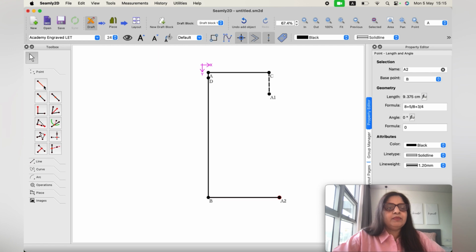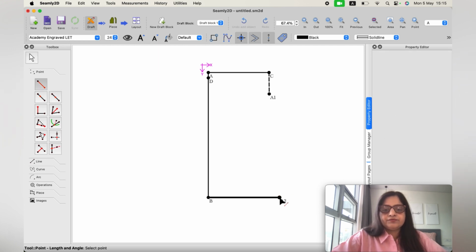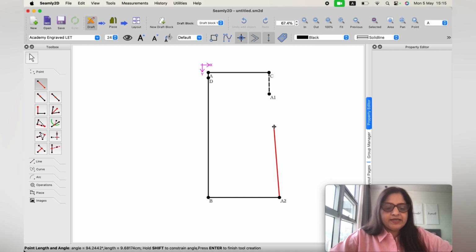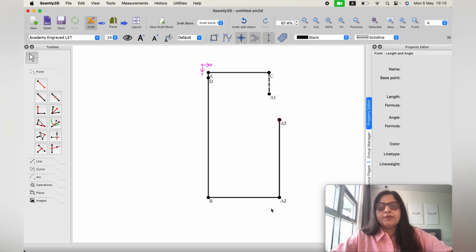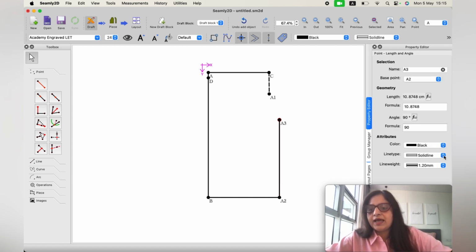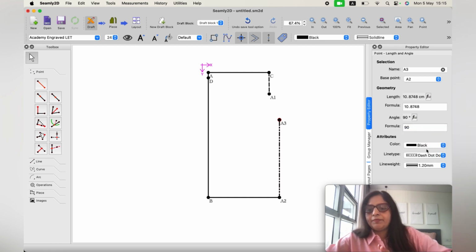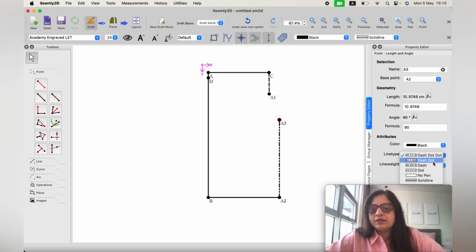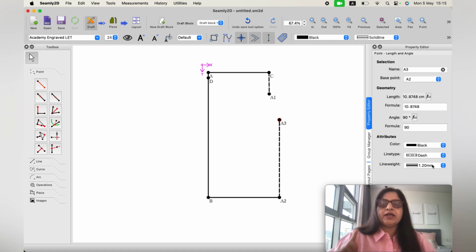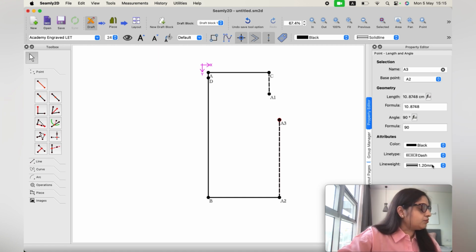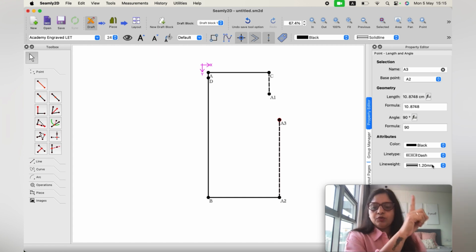So I'll take randomly 9 to 10 inches above from here. It is very easy to take a straight line up here. I'll simply hold down the shift key and put a mark here. Okay, it is coming to something like 10.8. I am keeping it as it is. I'll change the line type to dash again, because it is not exactly part of our pattern. So this is our figure 1 of the back bodice draft ready; in the book it is figure 6.